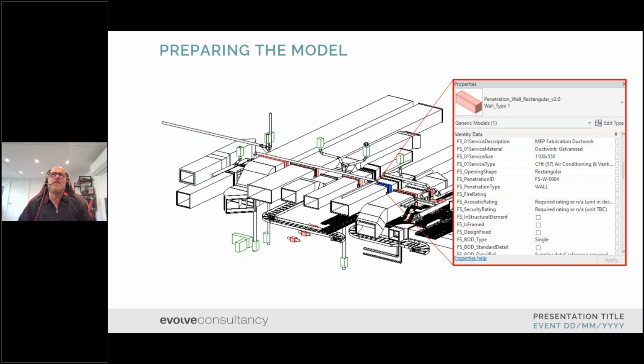So what I've done is gone through just a couple of slides here to show you the kind of considerations you need to take into account to get the most from these rules. Now, that's not saying you have to have answers to all these questions that I'm going to pose in just a second, because it really does depend on where you are in the project and what you're trying to achieve. For example, the fire stopping rules have no consideration whether you are working with complete manufacturers' fire stopping objects, or you're just working with builders work placeholders at early design stages. The rules don't care. What you have to do is identify what the objects are and then work with the data you've got to get the results out.